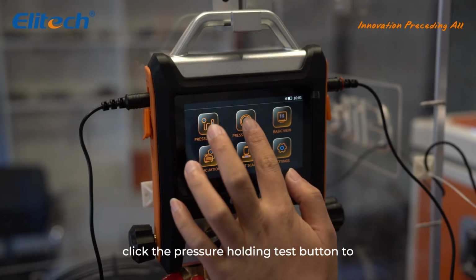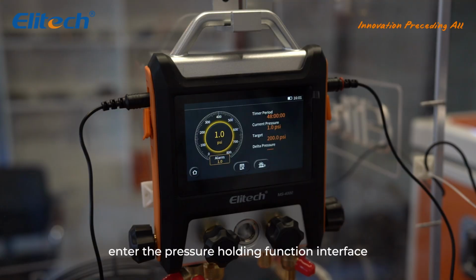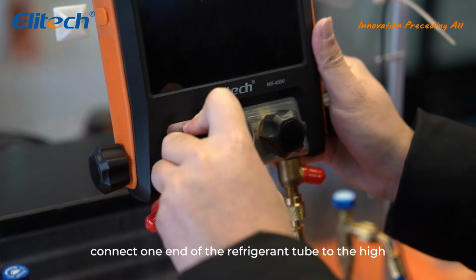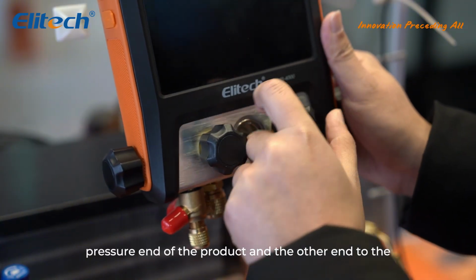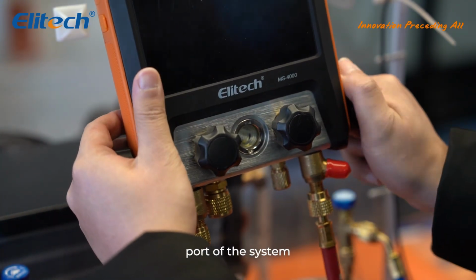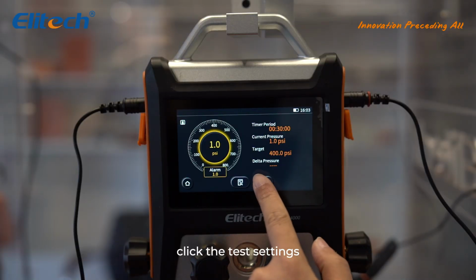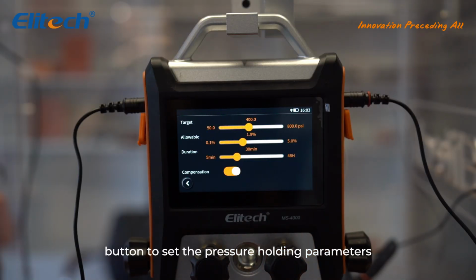Pressure holding test. Click the pressure holding test button to enter the pressure holding function interface. When performing pressure holding, connect one end of the refrigerant tube to the high pressure end of the product and the other end to the pressure holding port of the system. Close all valves. Set the pressure holding parameters. Click the settings button to set the pressure holding parameters.